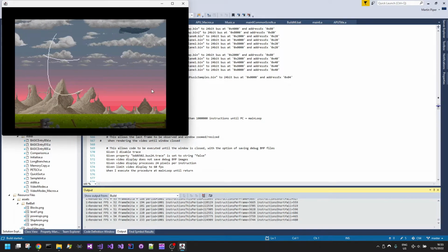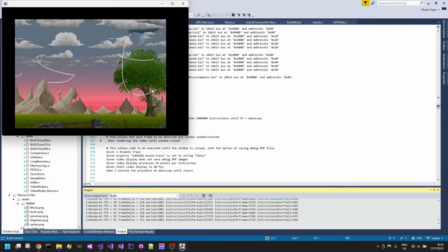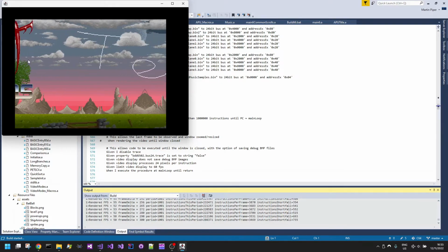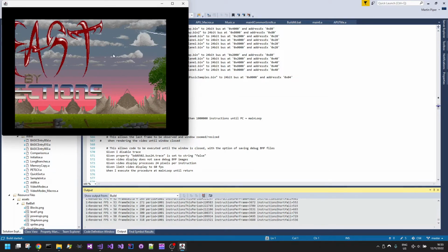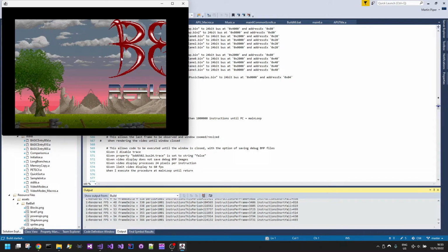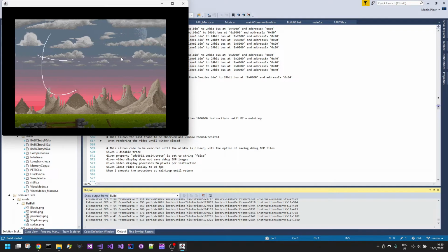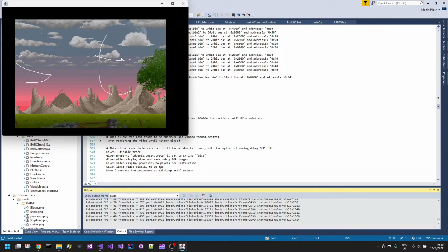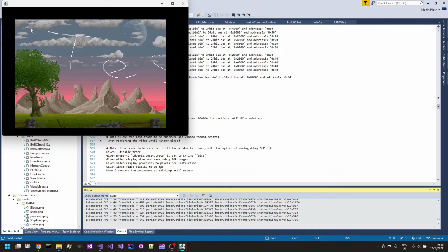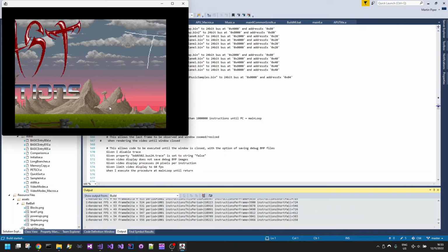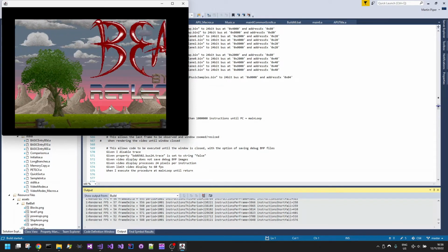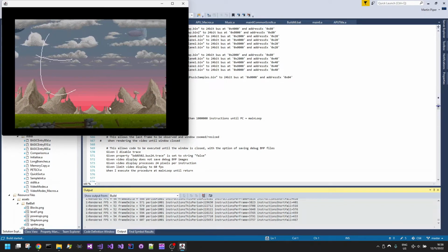I'm using this to demonstrate and to also test out the functionality primarily of the APU, which is an advanced processing unit, which is like a co-processor, if you like. It runs in parallel with the main CPU found inside the Commodore 64, but its sole purpose is to wait for specific positions on the horizontal and vertical position on the screen, and then to, as quickly as possible, update the external memory in the video or audio hardware.